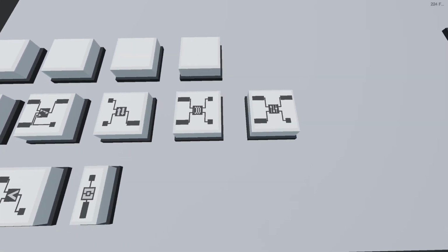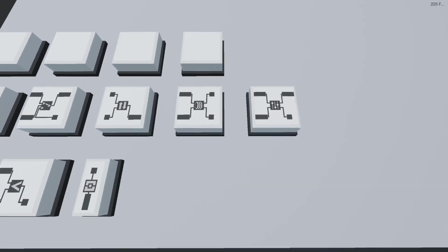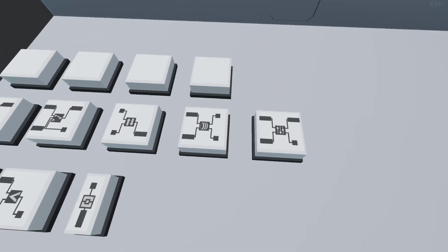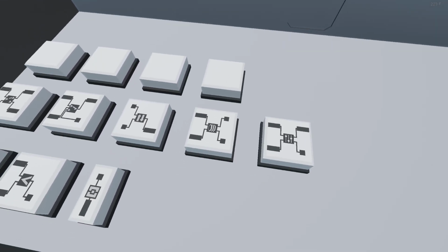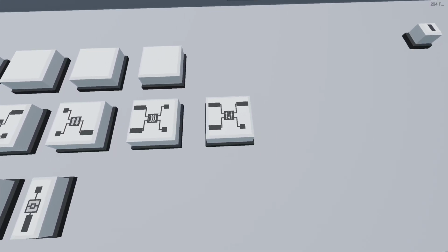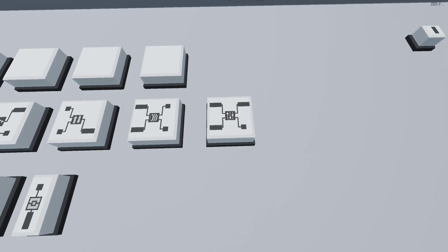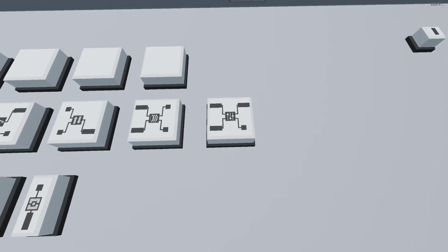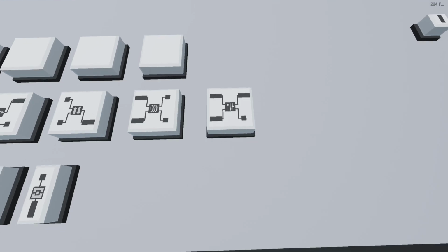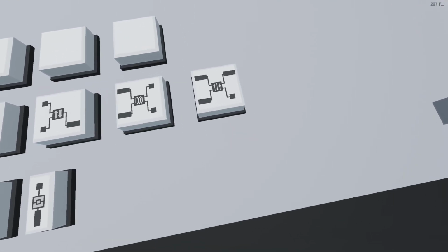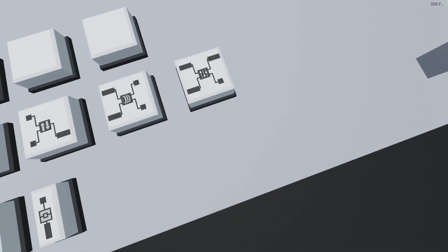You then have the memory register, which can take a value, which you can set it to remember at any given point, and then recall it out to somewhere, and then you can clear it and set in a new one with the on-off inputs. Then you have the PID, which, depending on the values of your set value and the value of your process variable, it will change its output to control a system as you want it to. You can activate it through the on-off system to make sure whether it works or not.